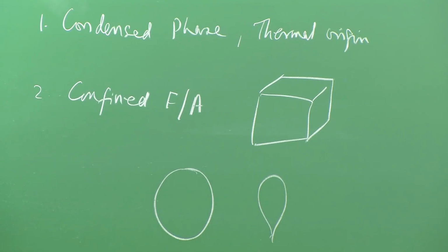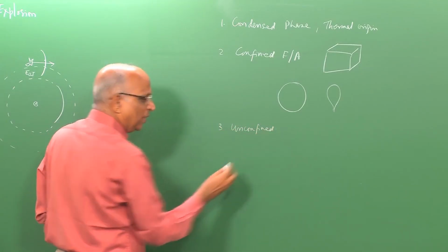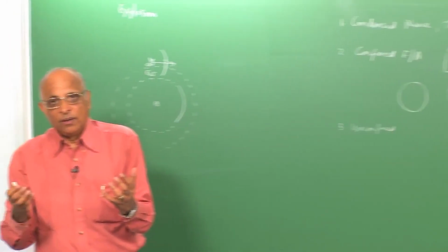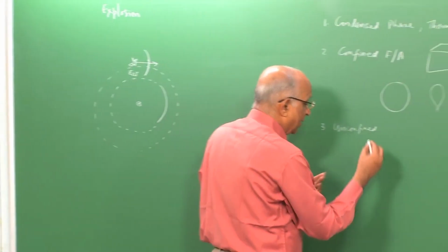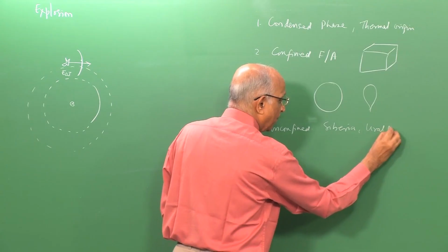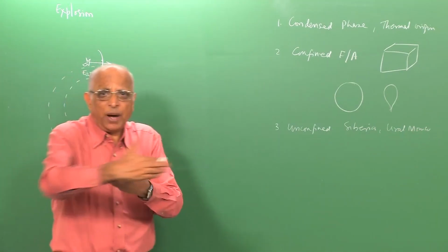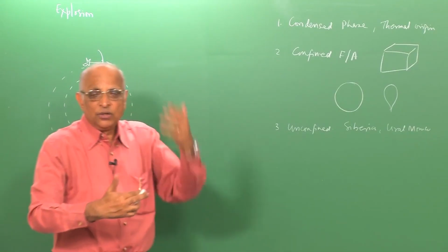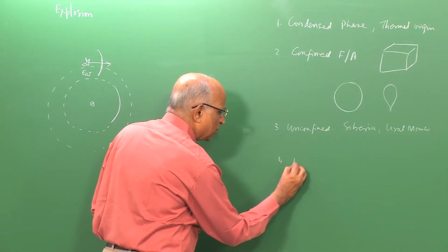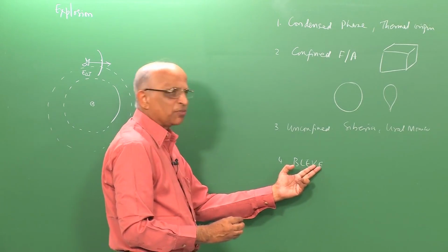Third, we said it could also be unconfined. In case of unconfined, we looked at spillage taking place or gas getting spilled, such as the one we saw in Siberia, in the Ural mountains, wherein there was this spillage. The spillage goes along the ground, two trains pass in the opposite direction, they mix it with air, you have the spark and it explodes. These are unconfined. The fourth one, what we considered was BLEVE, boiling liquid expanding vapor explosions.